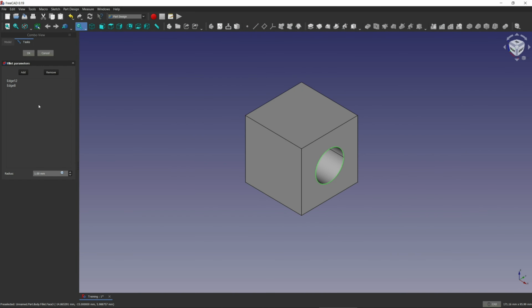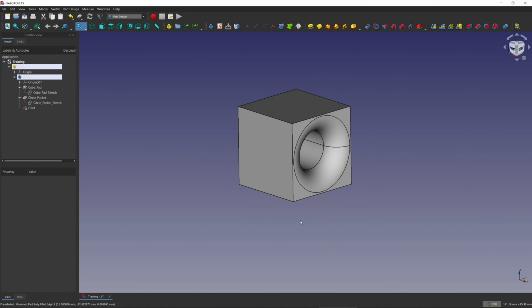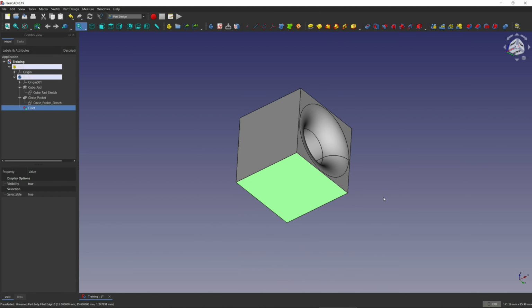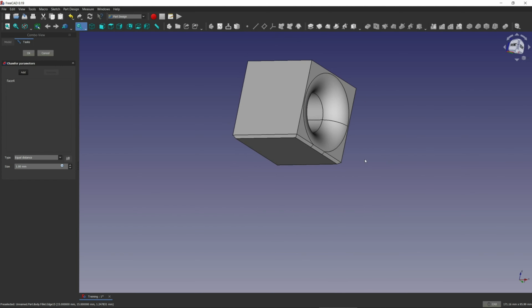So what's the difference between the Fillet Tool and the Chamfer Tool? So the Fillet Tool adds a radius, which is what you can see right now. And the Chamfer Tool will just cut a straight line from 2 points. So at the bottom, you have a chamfer, where it's just chopped a chunk of material off of that edge in a straight line.